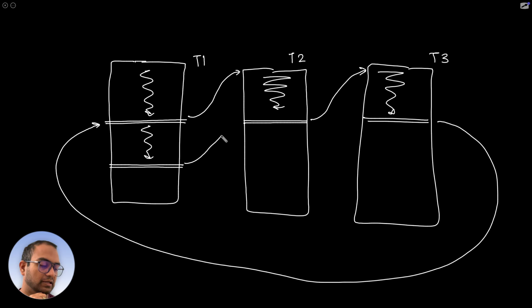So anyways, the idea being, if the program counter can be restored to this value, then it can continue to execute T1. So the important information here is PC is involved, and then we are saying, some trick to changing PC is involved. And the third thing, which I'll write down here, is when from T3 we were wanting to return to T1, we wanted to essentially go back to the location A, or A plus 4. So then the idea is, somehow we should be saving